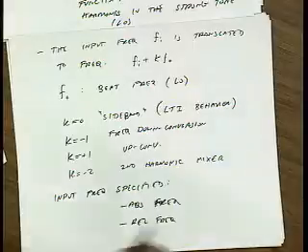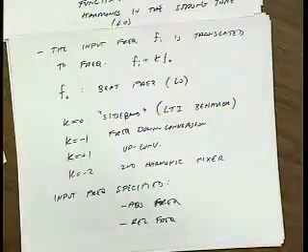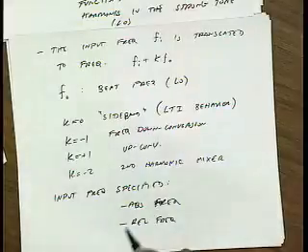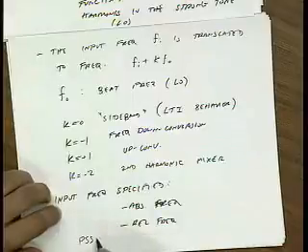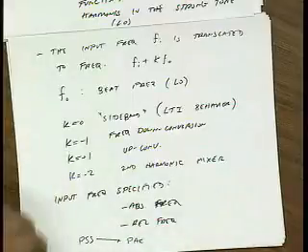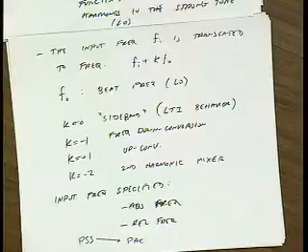Pretty clear? Yes. So PAC is a subset of PSS, or? Yeah. You have to first run PSS. So when you run AC analysis, you first have to run DC analysis, right? You need to find the DC operating point. So first you run PSS, and then you run PAC. So you can't just run PAC without running PSS. It's a good point.